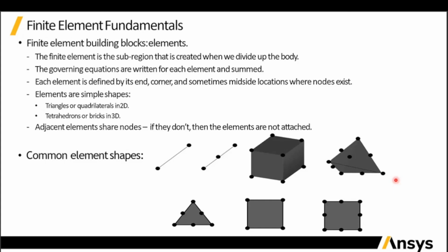The finite element is a sub-region that is created when we divide up the body. The governing equations are written for each element, and at the end those are summed. Each element is defined by its end, corner, and sometimes mid-side locations where nodes exist.